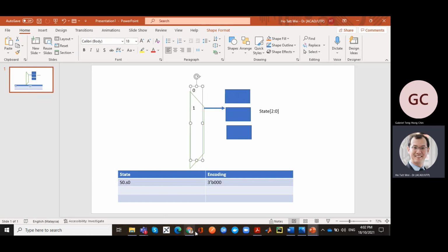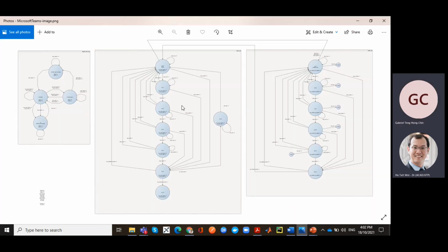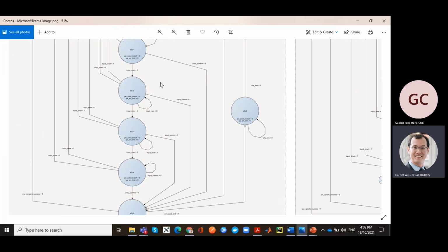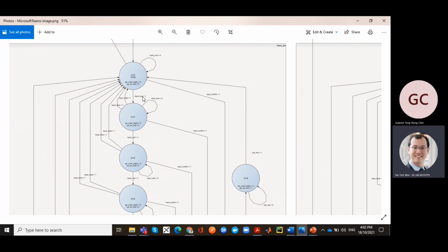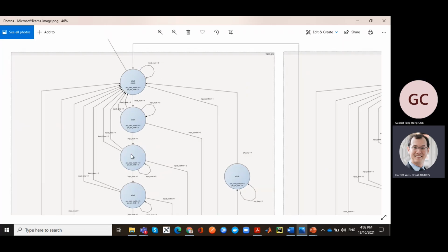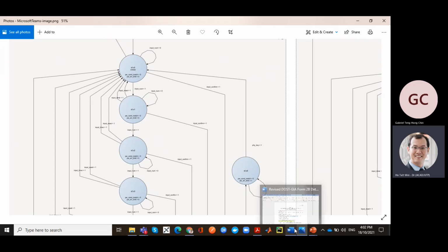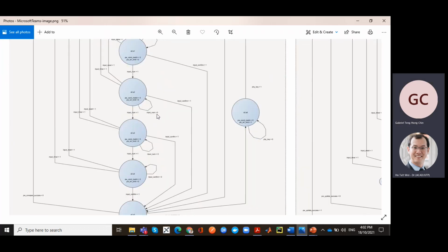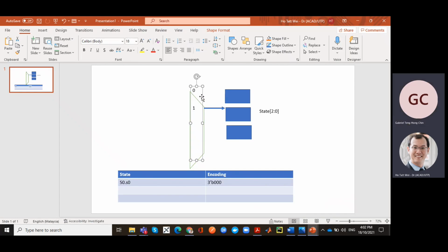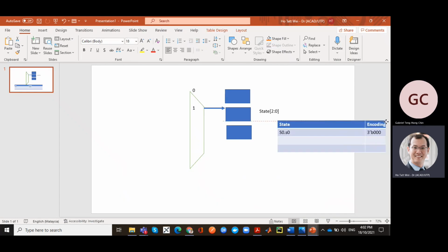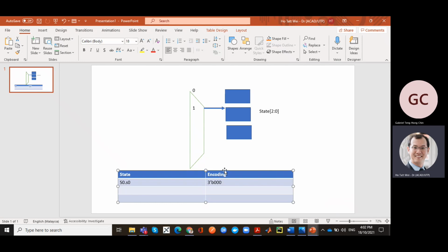Let's look at your state transition diagram and look at your inputs. You transition on input num, input timer, input reset. So there are 3 conditions that will cause the state transitions, right? Input num, input confirm, input reset, input timer. So these are the 4 conditions that will cause state transitions. Since they're the 4 conditions that cause state transitions, they go into the conditional side of your multiplexer.